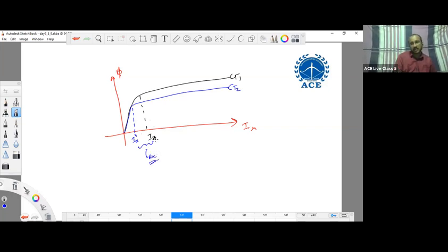Due to this difference of saturations, current results in the relay, and the relay operates even when the fault is taking place outside the zone.